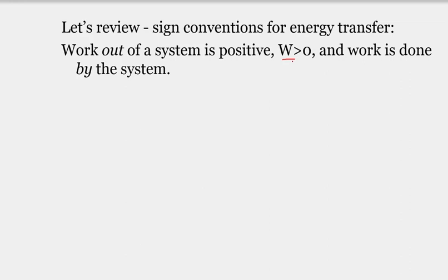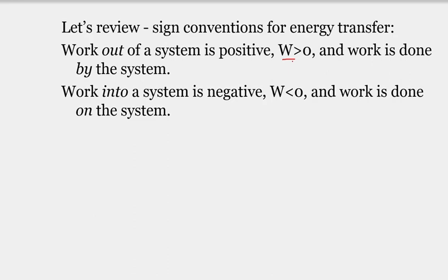So my turbine, if it's generating power, which we kind of hope all turbines are generating power, that would be work out of the system. It would be a positive term. If the work is into the system, like when we compress a gas, like we do in an engine, then that term is negative. That would give us a numerical value less than zero, and the work is done on the system.